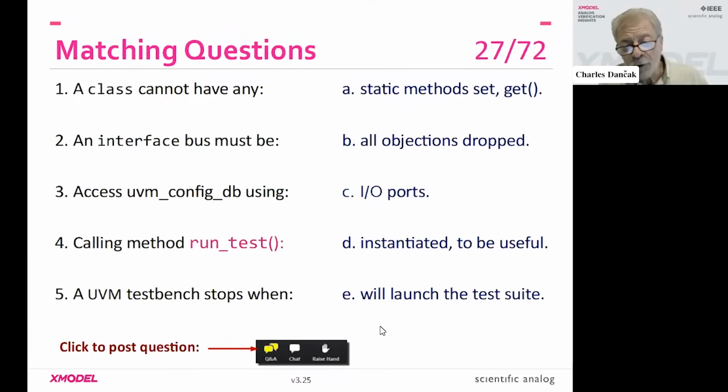And we carry over the same concept to UVM testbenches. Our interface bus is certainly not synthesizable because we've got real signals thrown in there, but it's the same idea. It's a way to collect all the related signals together and still be able to access them individually.